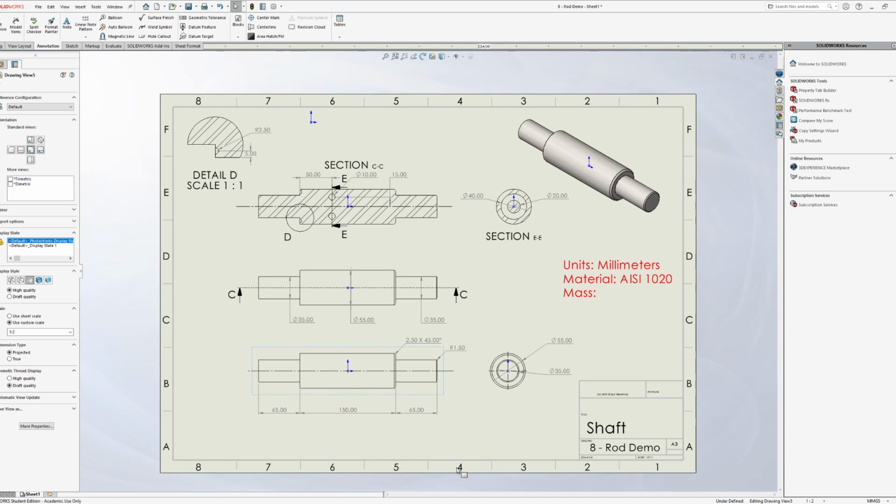So then the drawing and the part, I mean, there's no need to do a pack and go. You can literally just save both of them. If I wanted to do these two here, just in this folder, I could do run demo and then save, and then I can have include drawings. I could do all this stuff, or I could use the pack and go, but it's definitely not necessary. Super cool, it's yelling at me. So maybe we shouldn't use pack and go anymore, or as much as possible.